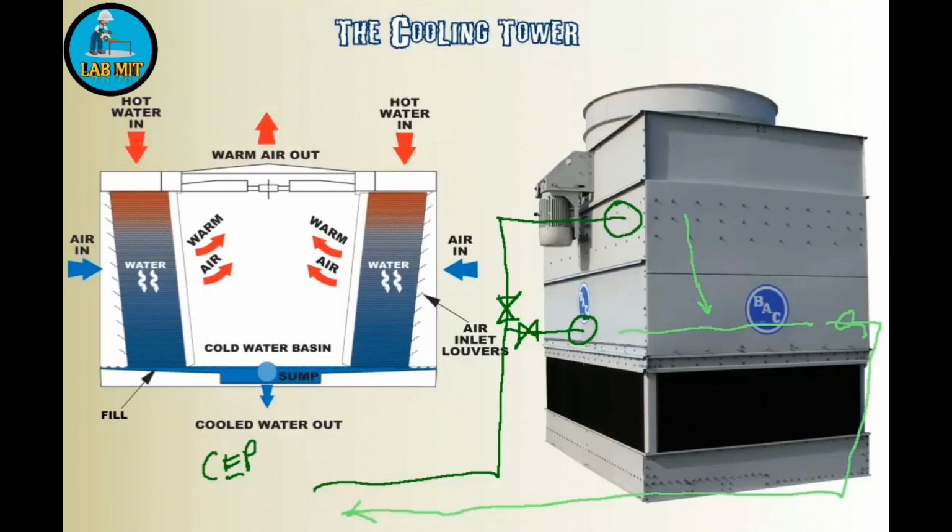If you make the water too cold, the efficiency of the chiller actually degrades. It's kind of like your unit at your house. If you run your AC when it's really cold outside, bad things start to happen. You're running the refrigeration cycle the wrong way. So essentially, they use that warm water to come right back in and send it back to the chiller, but still maintaining the required set point, whatever that may be. So that's one other strategy that's used with cooling towers.